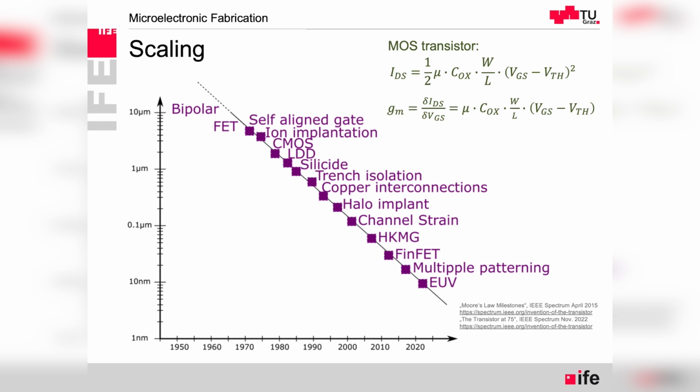We have this, for example, in a p-channel transistor, where source and drain are P, but also we have an extended layer under the gate of just lightly doped P. And that changes a lot the electric field distribution in the transistor. And it's also a topic for which you can find lots of information in the literature.